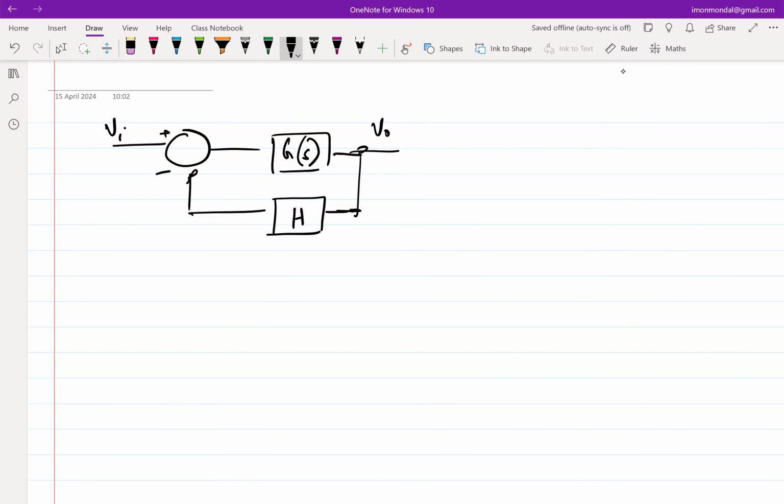And when we say that we resort to semi-graphical methods, we essentially say that we'll evaluate the loop gain, that is the open loop transfer function. How do you evaluate loop gain? So you have to first ground the input. It's not necessary to have an input because loop gain is a property of the loop. Input is irrelevant. In this block diagram, you can break the loop anywhere because there is no loading effect in a block diagram.